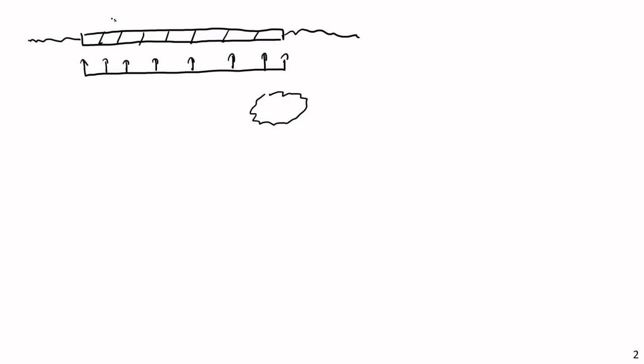Well, you don't have to be a structural engineer to realize that if you have one side of your foundation that has much less support than the other side, this thing is going to tend to tilt downward like this. So your foundation is going to tend to rotate, it's going to tend to deflect. Again, if I'm assuming uniform capacity across, I'm going to have deformation downward like this.